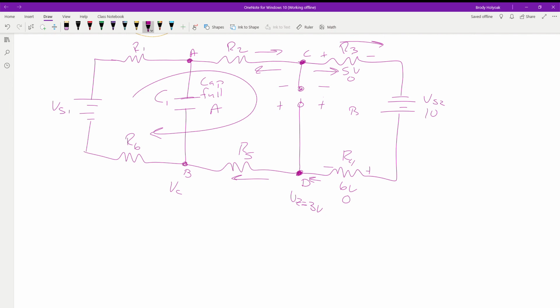All you're given is your sources, the resistor values, what kind of diode it is, if it's a Zener or not, and what the rating of it is. And I don't even think you're given a capacitor value, because we don't care about the capacitance value at this point. There's only one capacitor in there. So, again, remove the diode, find out the bias.